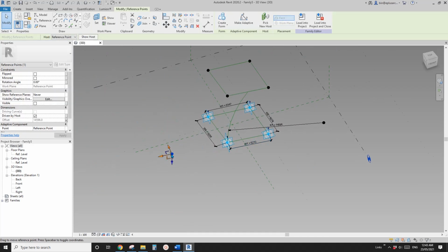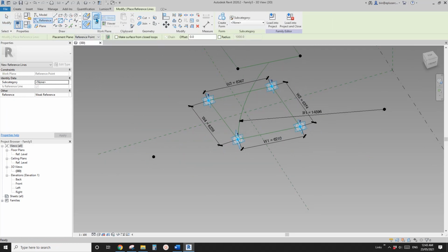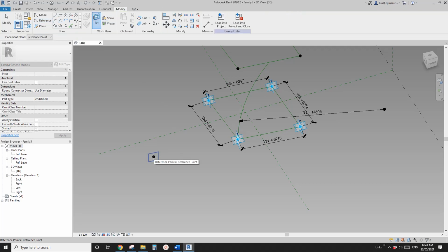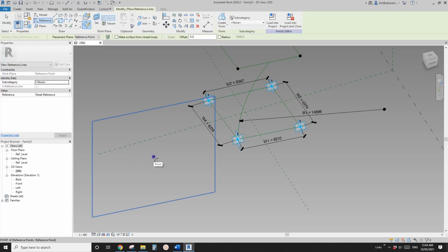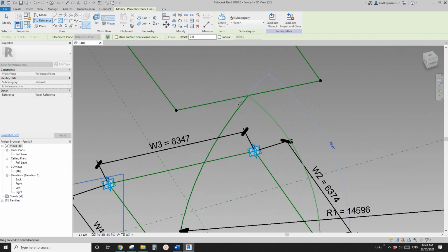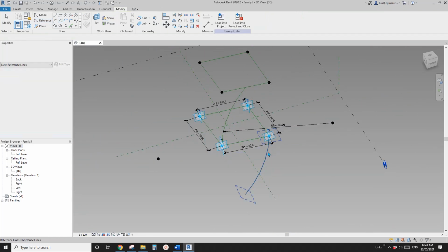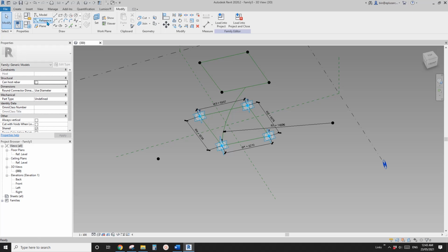So now you will see it comes to here, and reference arc, set work plane, tab, pick this work plane, start from this point, and then point 2, and then go up here. So make sure you pick stop not on this arc. Although they are the same, if you see this highlight, this horizontal reference line, you will be able to, oops, that's fine, let's do it again so it goes to the other direction.